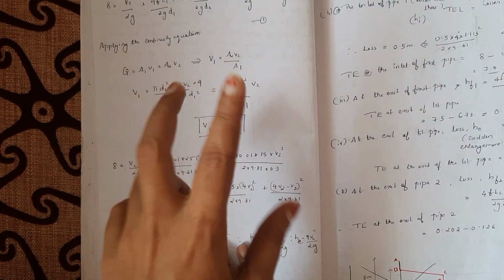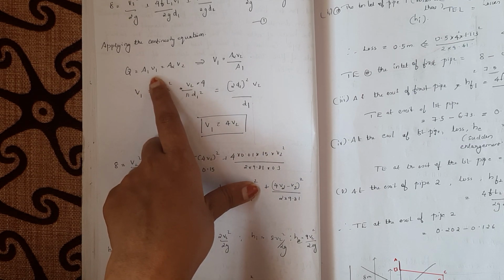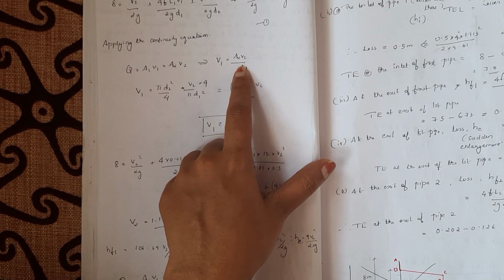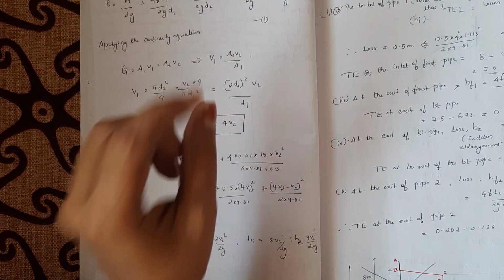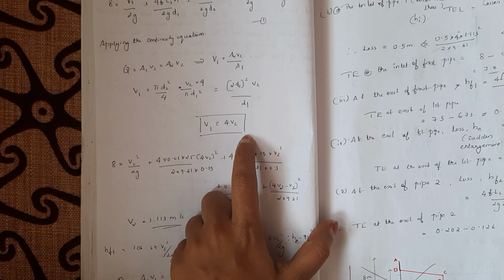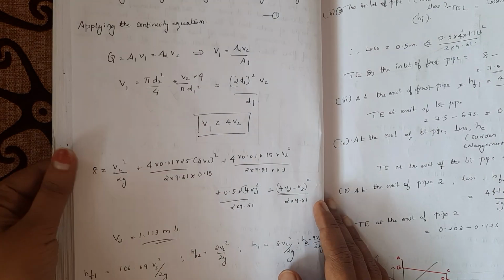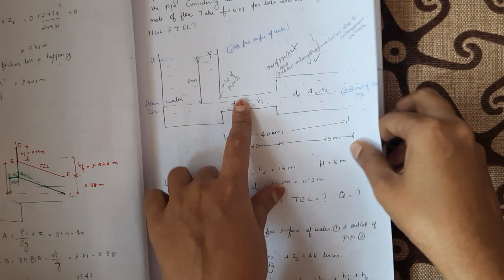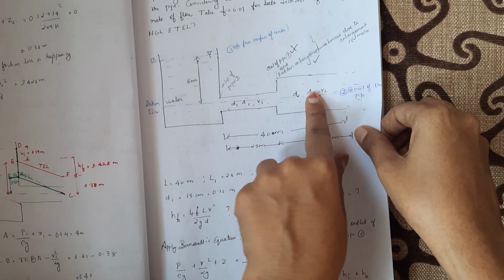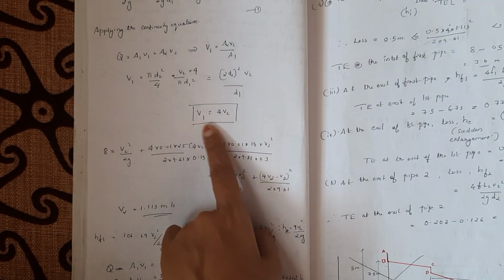We know that in both of those pipes, the discharge will be the same, isn't it? So A1 V1 is equal to A2 V2. We can equate both, and by writing V1 is equal to A2 V2 by A1 and substituting the values, we'll get something like V1 is equal to 4 times V2. What I've done here is I've taken D2 as 2 times D1, which is the case, right? See, this is 15 and this is 30 centimeter. So actually the diameter has been doubled here. So we can take it like that. So we'll get V1 in terms of V2 like this. V1 is equal to 4 V2.